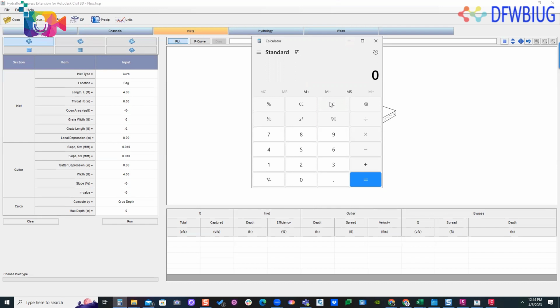I'm designing the pipe, and that inlet is on a grade, which means that it's not on a sag, it's on the road that's sloping down. And it also varies based on the slope of the road. Usually these roads, or most roads I'm looking at, are 1% or flatter. That number might go down even more if the slope is greater.